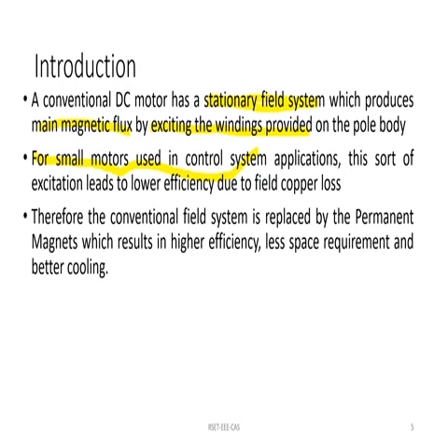So for these type of applications, we replace the conventional field winding system with permanent magnets, which thereby results in higher efficiency, less space requirement, and better cooling.